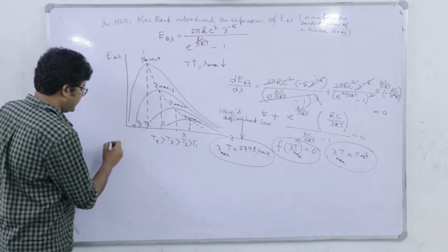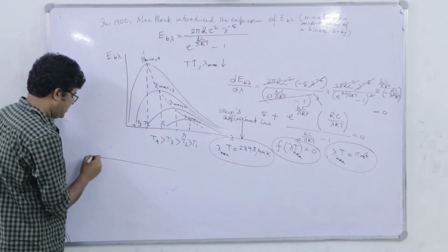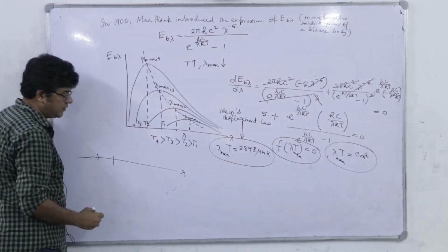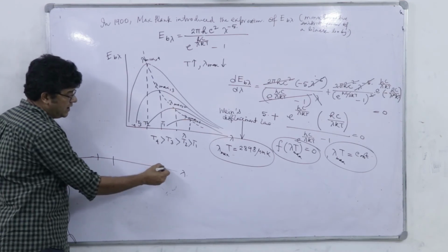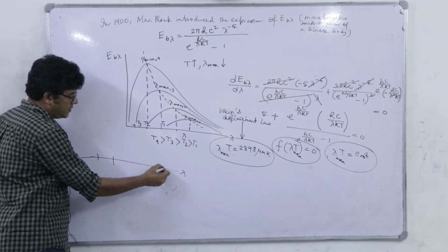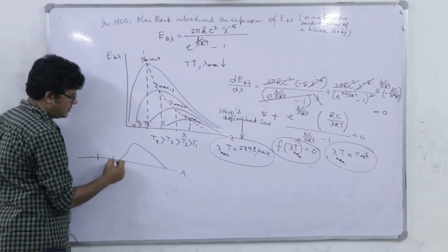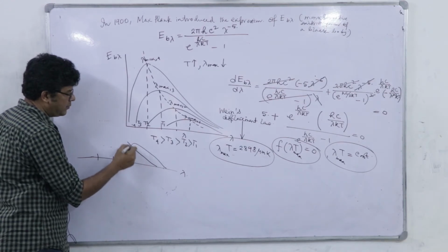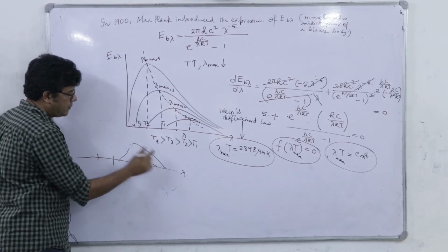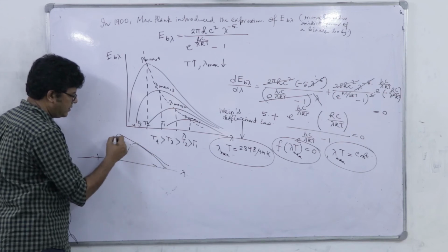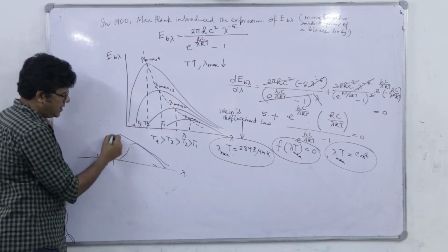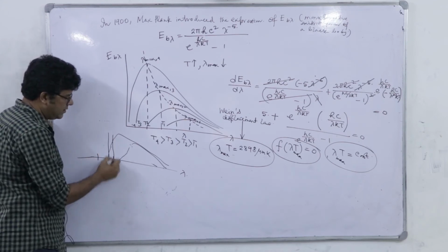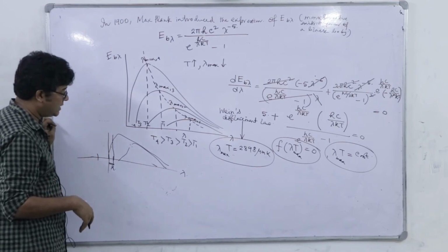So you see that if I think that this is the wavelength range and this is the narrow visible range, okay. So initially it's emitting something like this, so you can't see it. Next, as we go on increasing the temperature, it will emit something like this, and the body, say in VIBGYOR, this is the red band, so it will appear red hot, right?